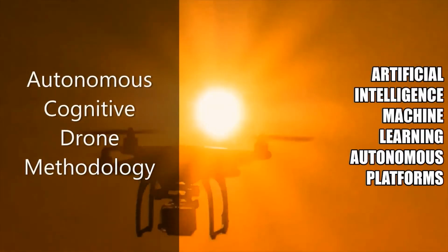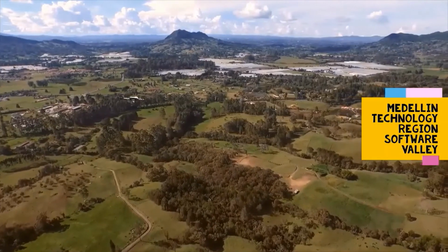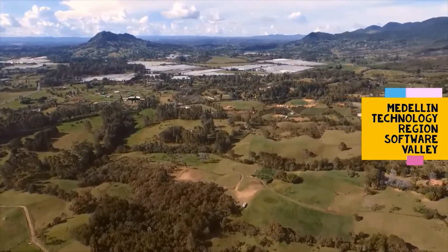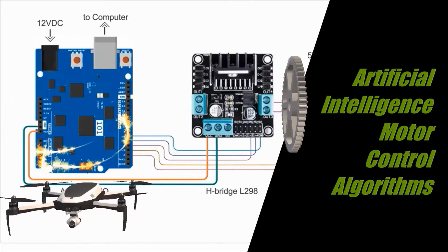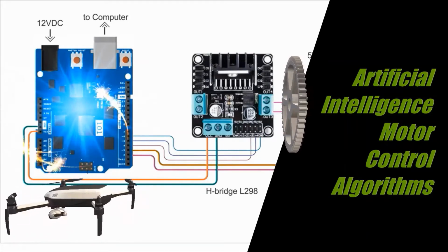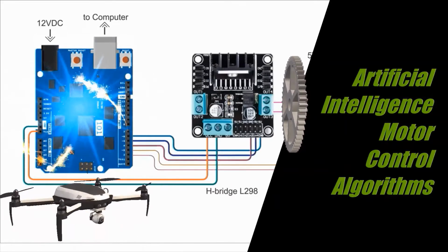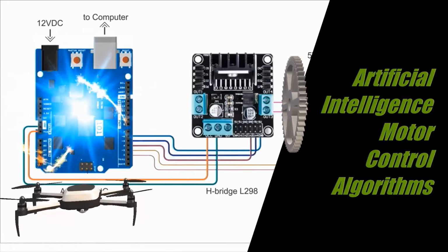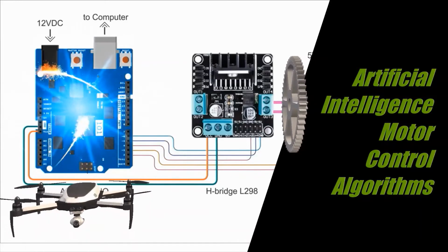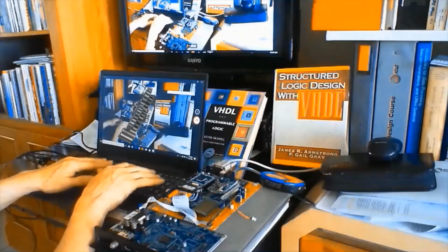At least one of the two magnetic fields is generated by a solenoid carrying a current, and the phase relationship, that is the rotor and stator magnetic field, such as the load angle, must always be greater than 0 degrees in order to keep the motor in motion. That is, negative angles reverse the rotation.